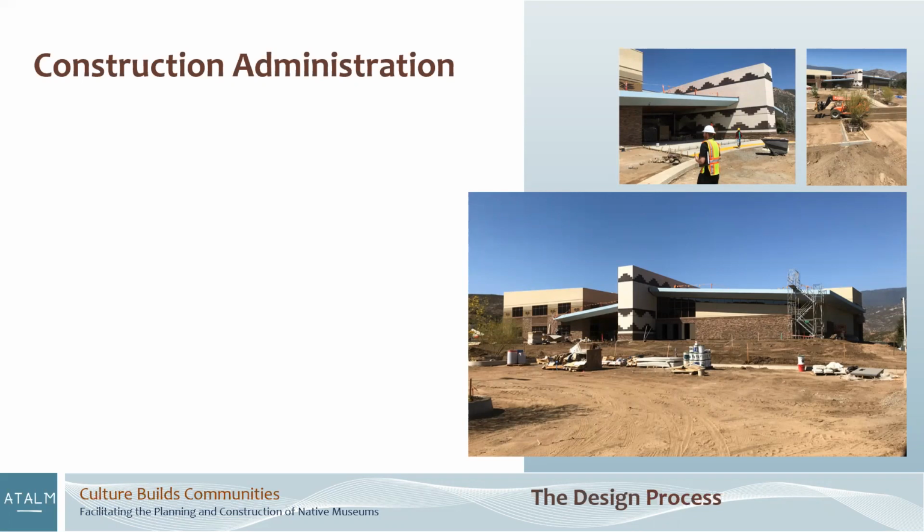And for an architect, it's construction administration. For the contractor, it's when they mobilize on the site, they get their trailers on, and they start rocking and rolling with earth movement first, digging foundations, pouring that, a basement if you have, getting it back up to grade, throwing up steel or concrete, whatever it is, and starting to skin the box.